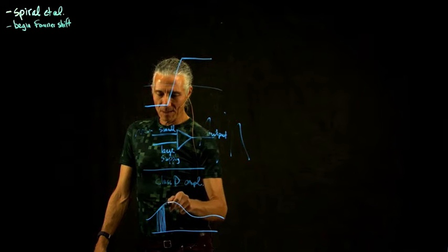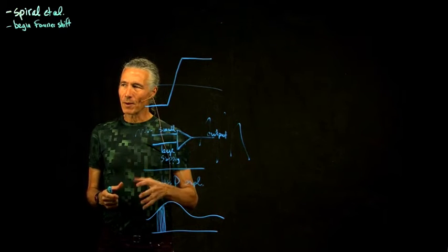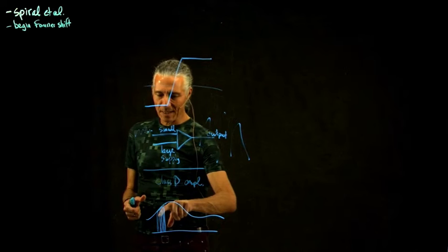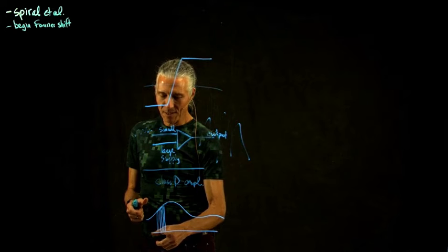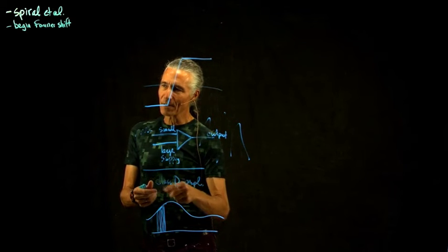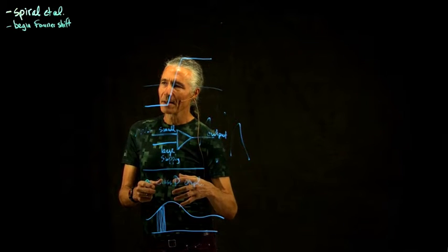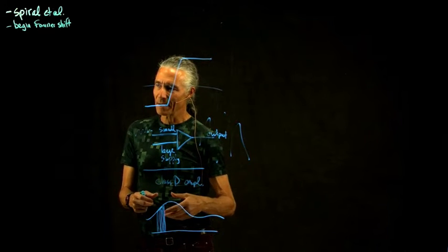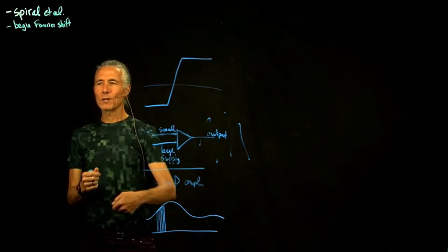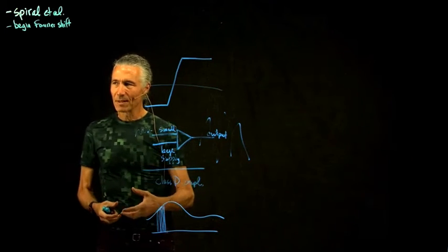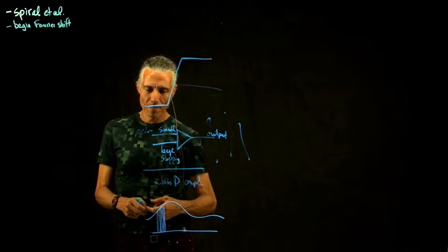It partly gets smoothed by the fact that the gradient coil itself has some dynamical properties when you put current in it. So the effect coming out of the gradient coil is actually very smooth, even though you put these little pulses into it. If you measure the magnetic field coming out of it, you don't see pulses because of the way that the current flows through a coil like that. Many of these things interact with themselves. If you start to put current through a coil, that's going to make a magnetic field, and then that magnetic field will affect the current you put into the coil. So there's like a feedback loop.